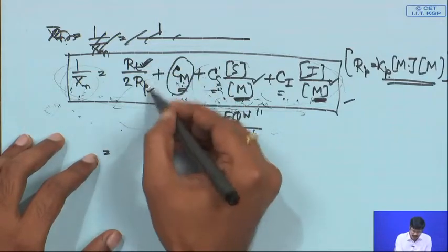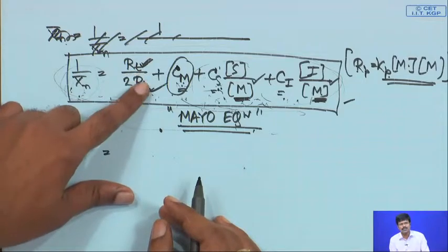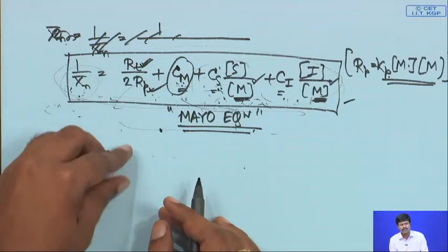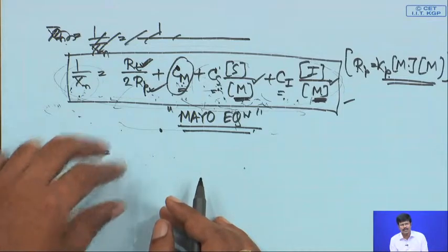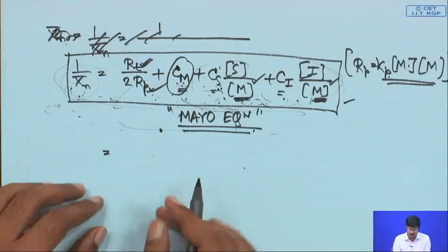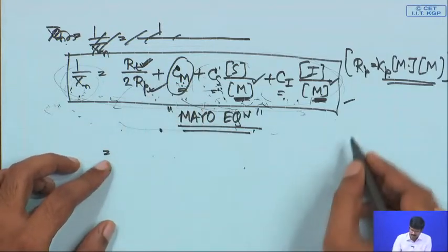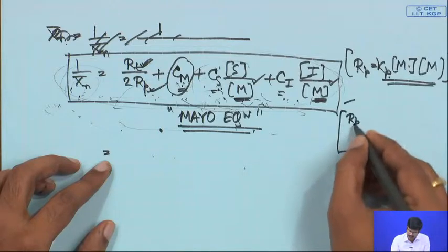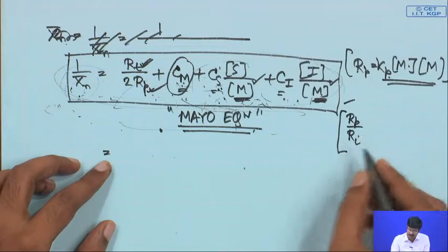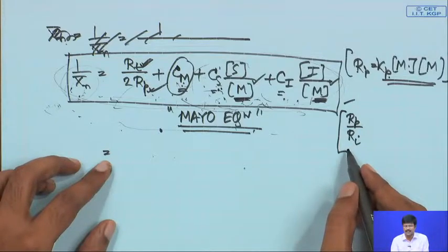Of course, R t and R p you can measure. We will not go into the details of how you can measure some of these things, but we will split it into different parameters and give you some idea about how some of them can be found out. So, this ratio, I will work here in the background: R p by R t is nothing but R p by R I, because rate of initiation equals the rate of termination, the steady state assumption.